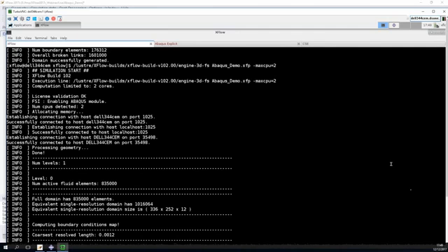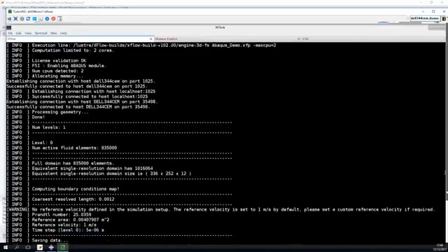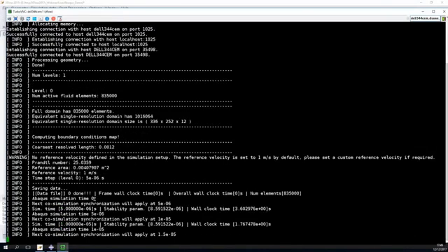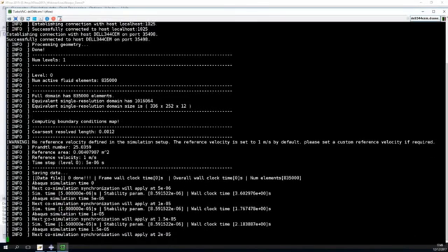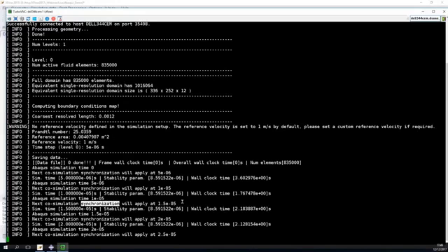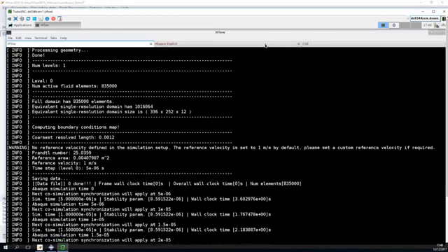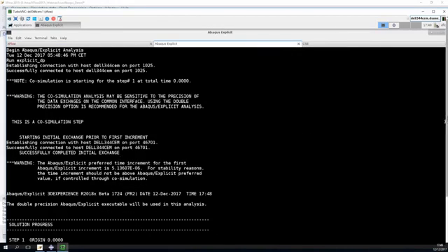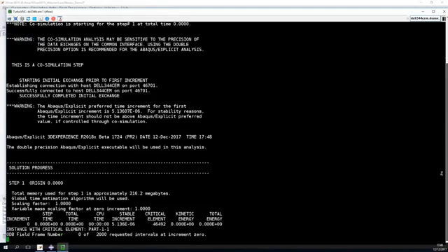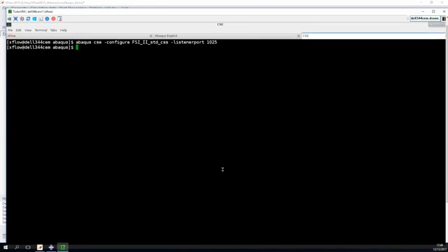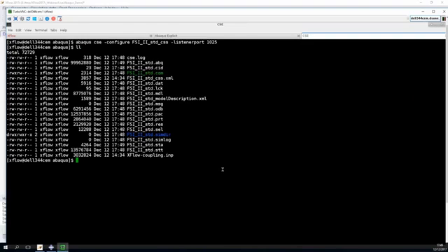Okay, so now the simulation is starting in the background. As you can see here, the simulation is advancing in time, and we have a synchronization point at each specific time step that the Cosimulation engine controls. Okay, so that was the XFlow log. This one is the Abaqus log file, and all of that is handled by the Cosimulation engine, which is